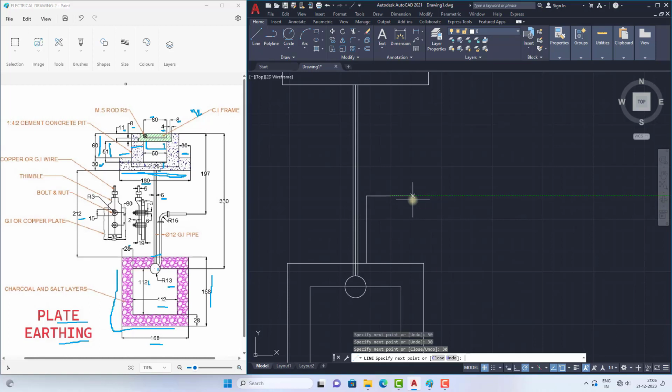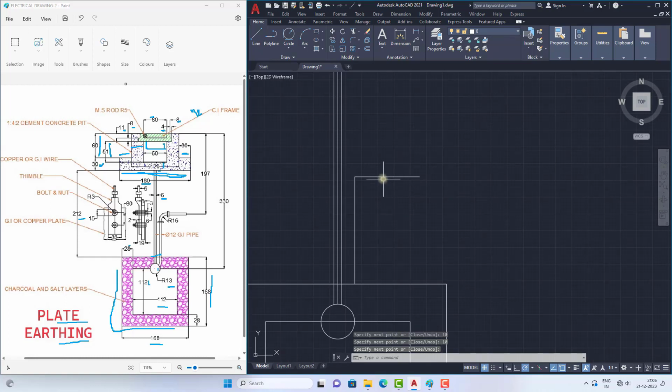So now see, now we can make a mirror. So I am joining lines, see, because we have drawn different types of lines. So give the command J and press enter. Select these lines. So if you select these lines and press enter, it will be converted into a single line.